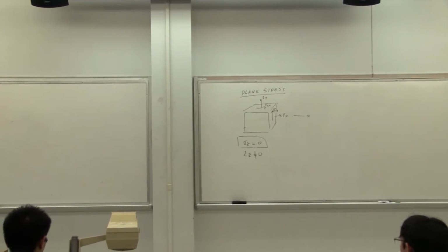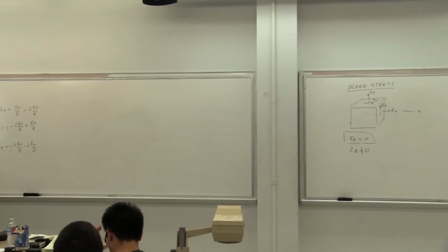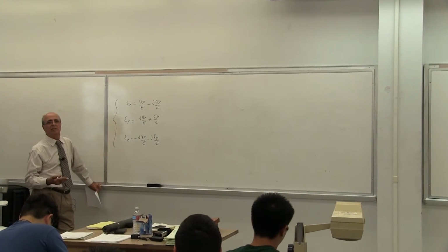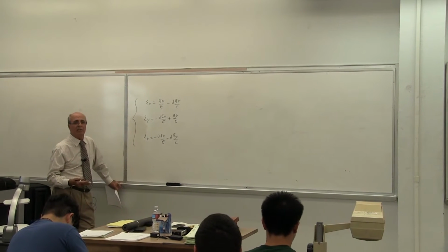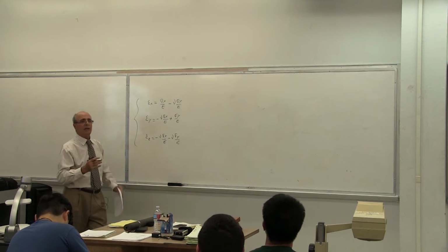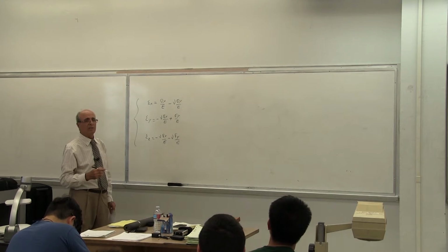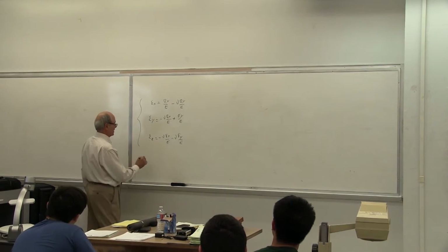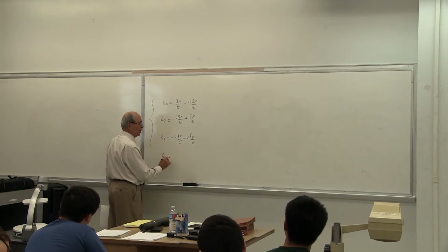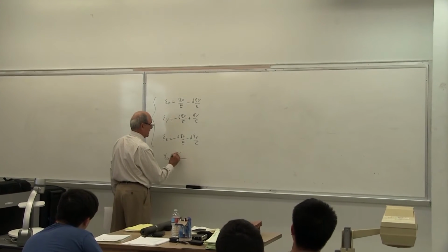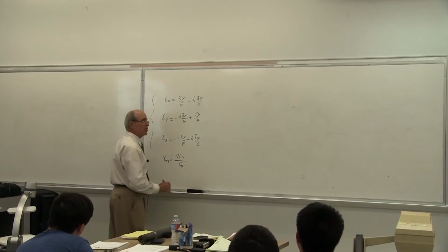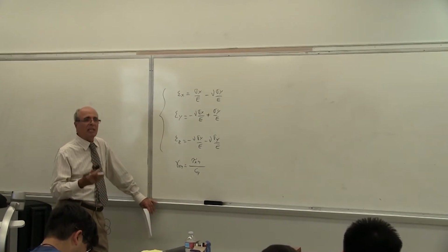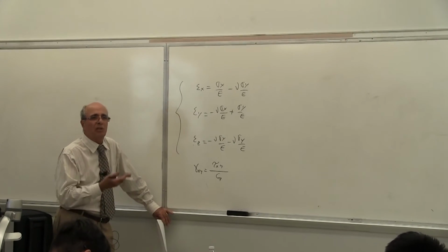These are what? These are the normal strains. What do we call this one? What are the normal strains? Is that correct or not? Or do we have a shear strain due to the tau? Yes? Remember those? What is that equation? Gamma xy equal to what? Tau xy divided by the modulus of rigidity. Yes or no? Correct? That's what I asked you over the weekend to study a little bit.